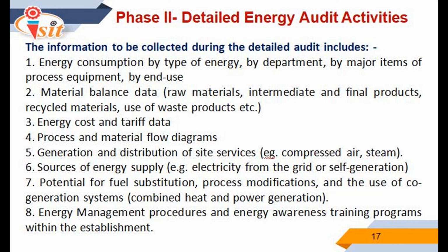The audit report will include a description of energy inputs and product outputs by major departments or by major processing functions, and will evaluate the efficiency of each step of the manufacturing process. Means of improving these efficiencies will be listed, and at least a preliminary assessment of the cost of improvement will be made, indicating the expected payback on any capital investment needed.